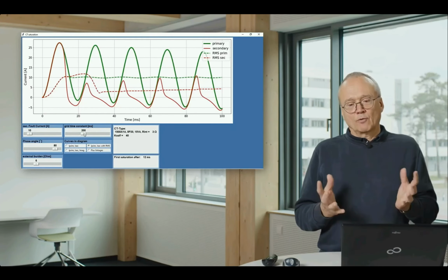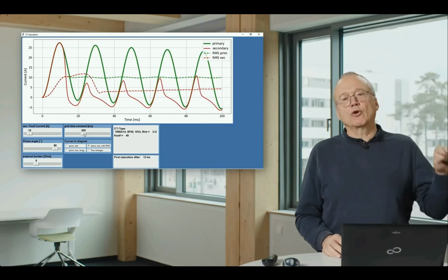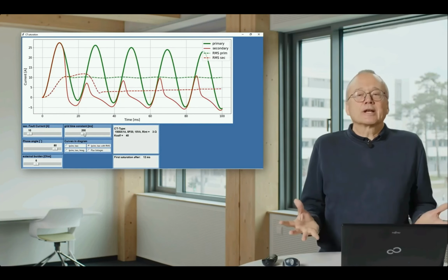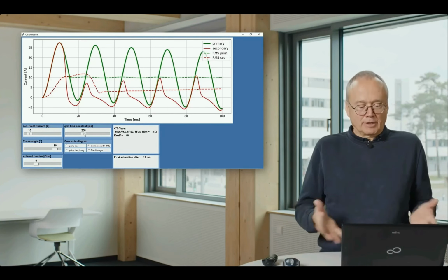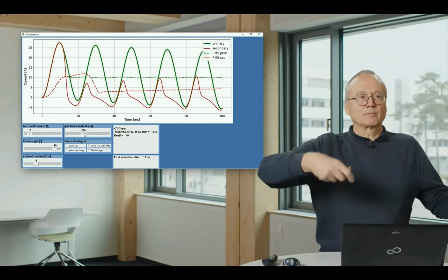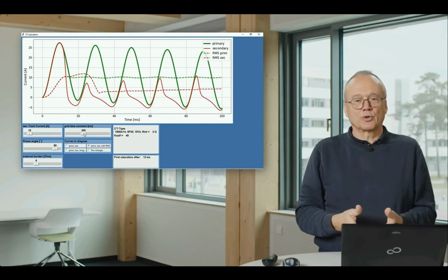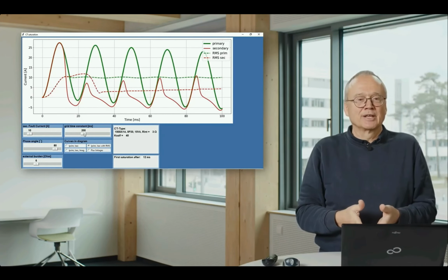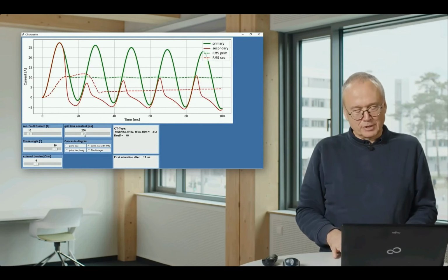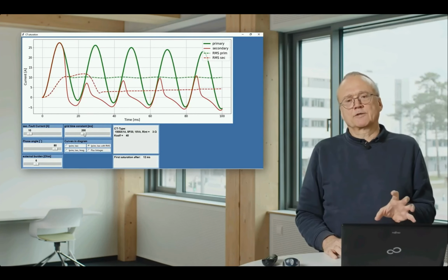networks? For that reason, we have to calculate the impedance of the short circuit loop in case of a short circuit. Theoretically, that's quite a complicated thing, because if we have a short circuit somewhere in the network, the current comes from a lot of generators through a lot of transformers and cables to the short circuit point. And now calculating that impedance by hand is pretty complicated, but we can do a few estimations.